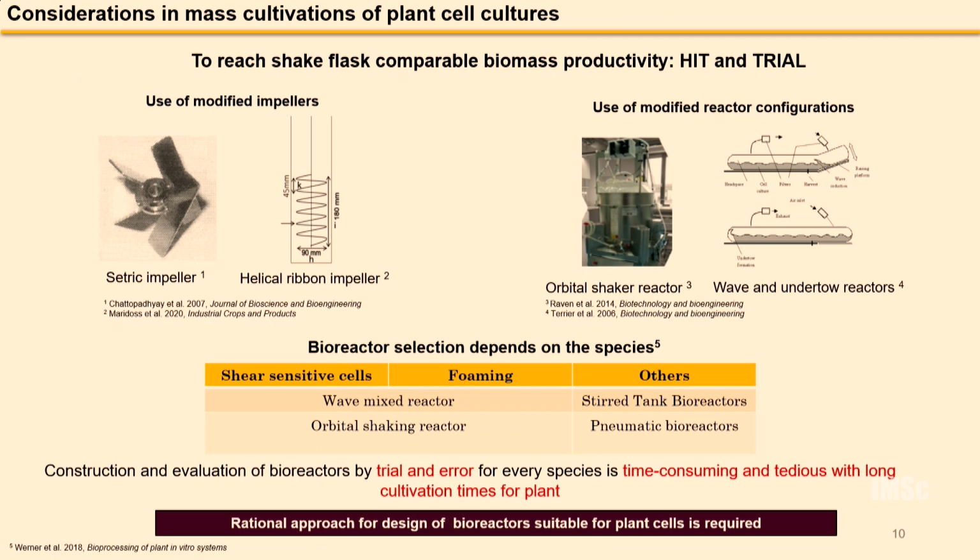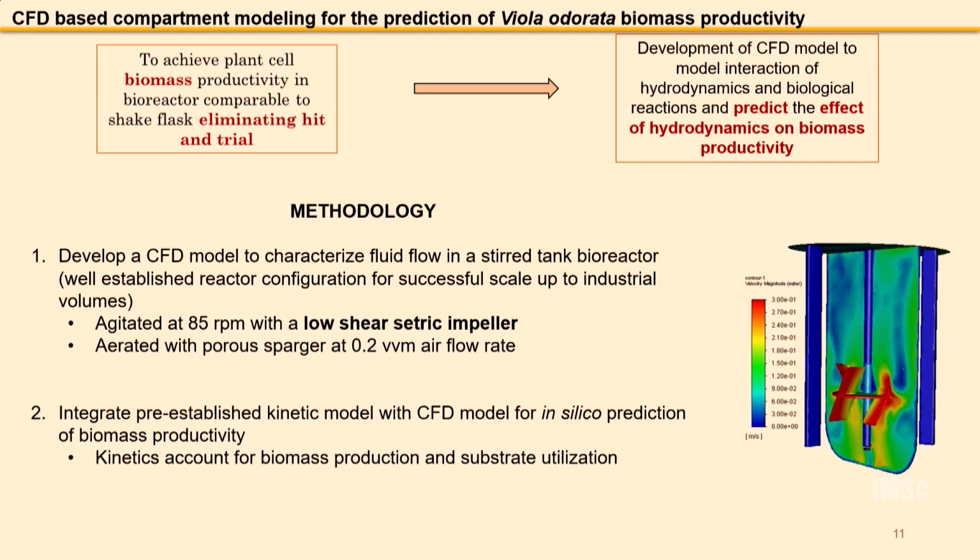It is not a common thing which can be useful for all the cultures, because some cultures have very good suspension ability, and some cultures have a lot of large aggregates. So it is again becoming a very species specific thing. If we are going to do it in a hit and trial manner, it is going to take a lot of time. So can we look for a rational approach? We have thought of using CFD to see the effect of hydrodynamics on the biological reactions by coupling the hydrodynamics, or the CFD data, with the kinetic model.